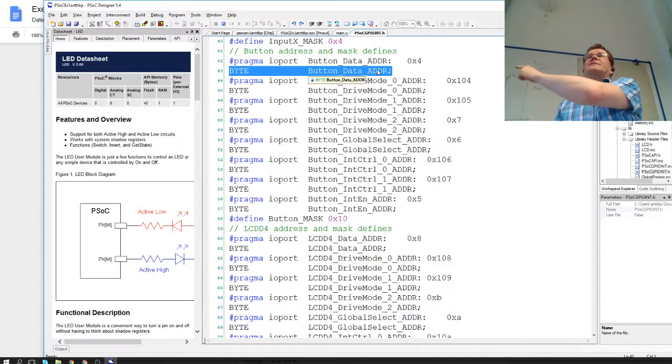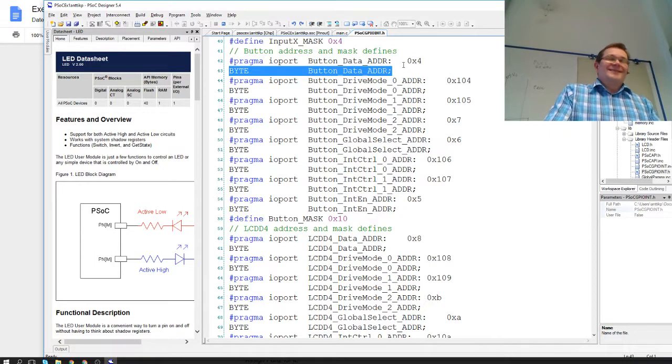You can also write the data on this variable at your own risk to change the initial state, for example. But then it wouldn't do anything. If you put the right value 1, it would affect the output port pin 1.1, and we have a pull down without any energy source here.